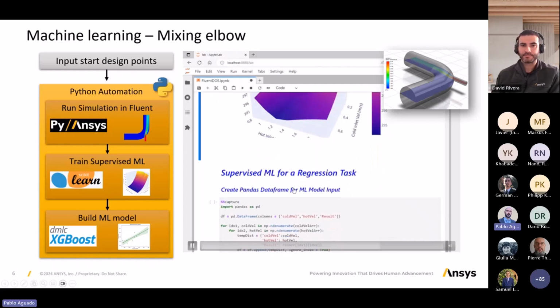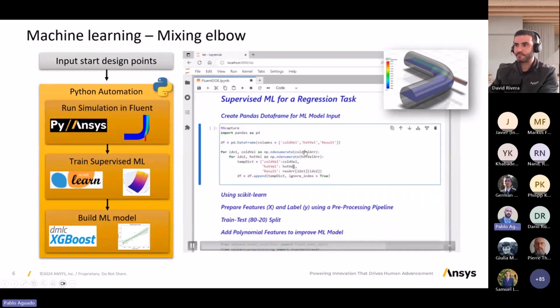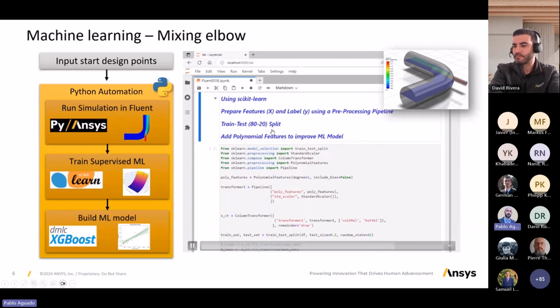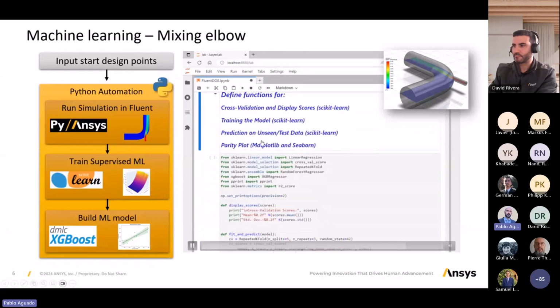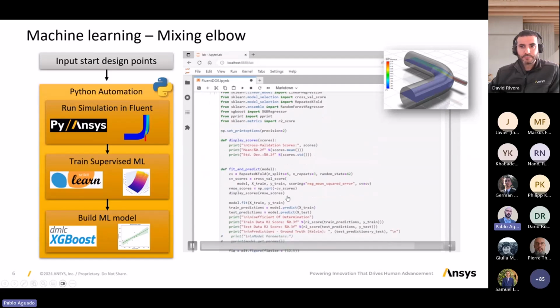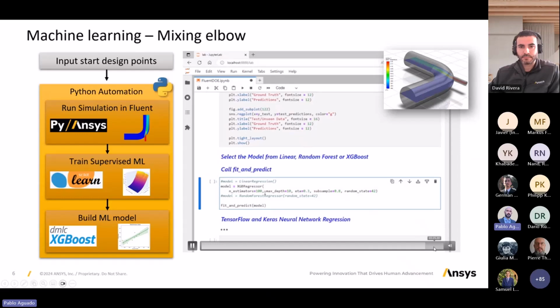algorithm. Then I can implement that in the regression library, provide that array of inputs and outputs, and it will create, using scikit, the trained model. So I split the data into training and testing, 80-20, and then I use that to train the model. Once it's been trained, it outputs a workable model that I can invoke, and with that I can create my 0D model that I can use as a neural network to get the response.